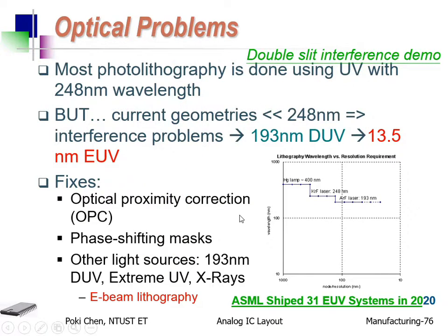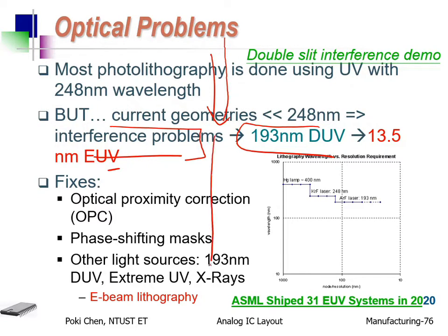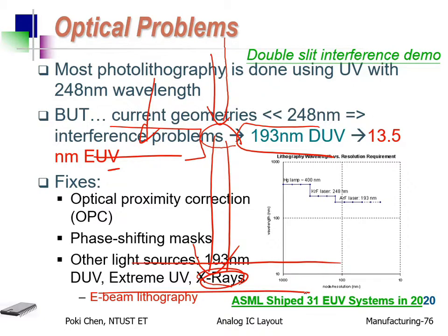Okay, so if, for example, this is the slit, then the light gets in, hopefully it goes through all the way. Then what you see will be what you get, because this is your photo mask and you have photoresist here. This white will become that white here if the light goes through directly from here to there.